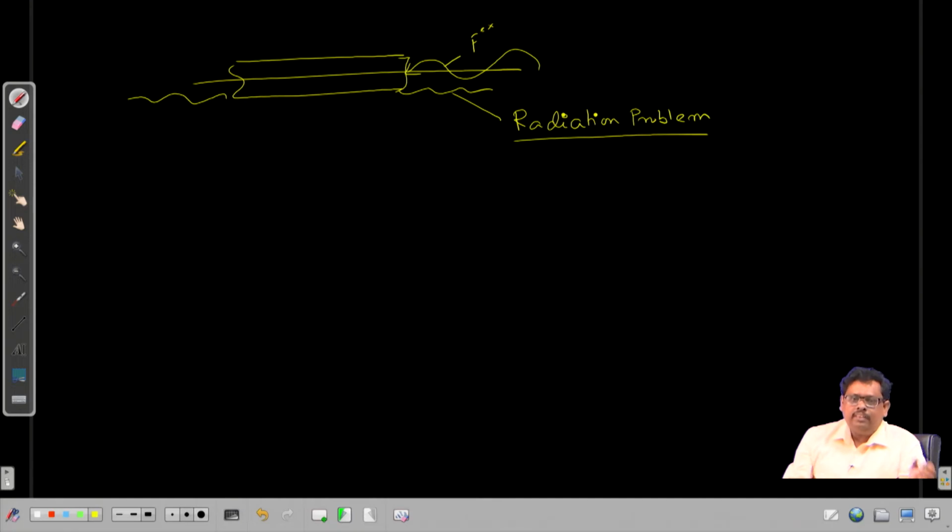Right. So, now let us see the picture. The picture is that the ship is very much stable here, there are no waves, and then suddenly the waves hit. That excites the ship and then the ship starts oscillating, and because the ship starts oscillating, we get some radiated wave, and this is called the radiation problem. Now, because of this phenomenon that the ship starts oscillating, this is the picture that we refer to when the